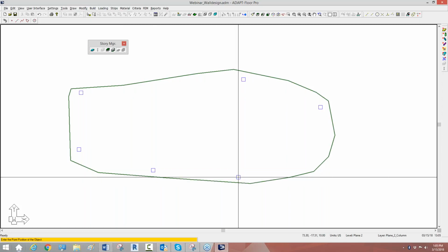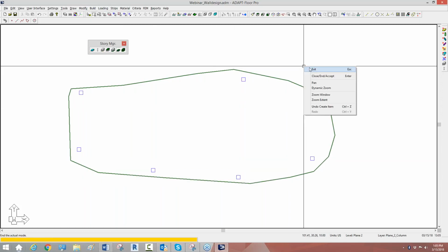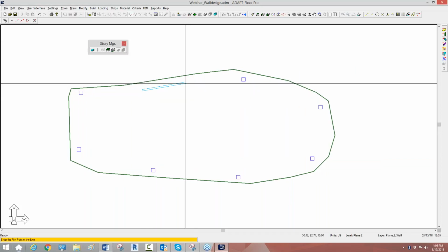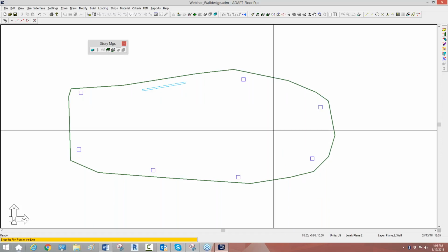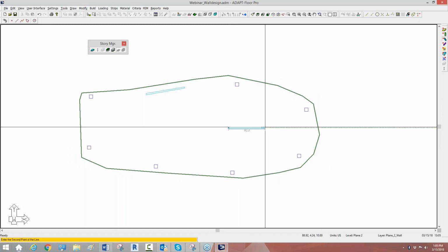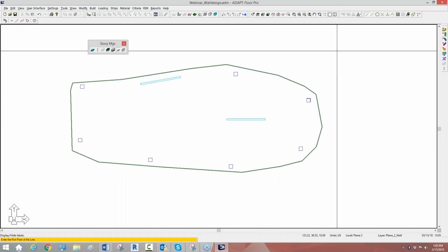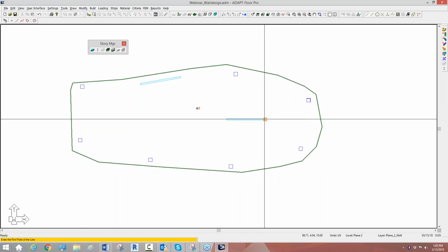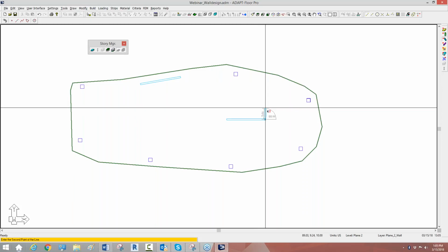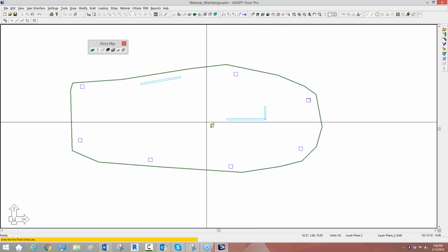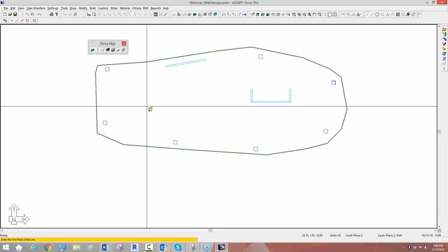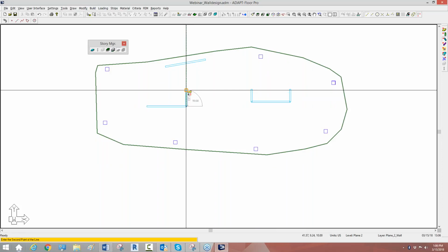We're going to have just a couple of wall groups in this case. I'm sure most of you have had practice in modeling in the software, so I'll kind of breeze through some of these different options and the tools we're using to create the model. And we're going to have walls. We'll do 3 wall groups, or we'll call them piers, where one pier will just be linear, the other pier will have multiple wall legs. So here's a 3-sided, or 3-legged, pier, and then we'll do another pier over here that might have just 2 sides.